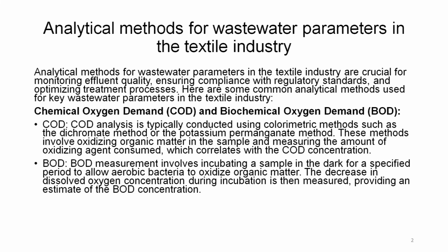These methods involve oxidizing organic matter in the sample and measuring the amount of oxidizing agent consumed, which correlates with the COD concentration. BOD measurement involves incubating a sample in the dark for a specified period to allow aerobic bacteria to oxidize organic matter. The decrease in dissolved oxygen concentration during incubation is then measured, providing an estimate of the BOD concentration.